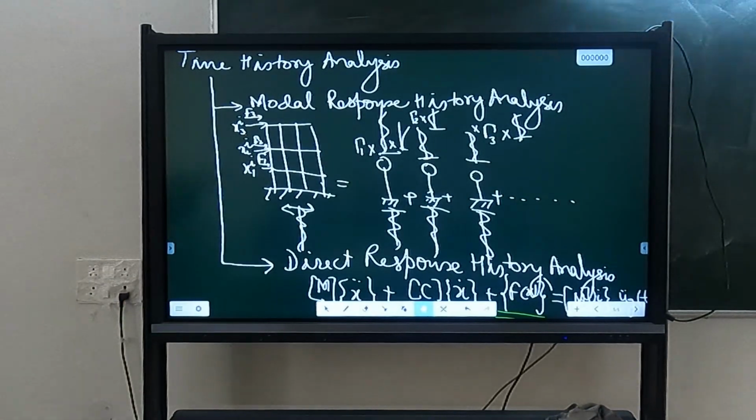Capacity curve you have obtained numerically, and in the numerical model you have assumed some model. What is a model? A model is also an assumption. We have assumed some backbone curve of our plastic hinge. We have not used hysteresis at all so far. But whether we use a backbone curve or hysteresis, that is an assumption. The actual plastic hinge may not behave in the same manner as we have assumed.